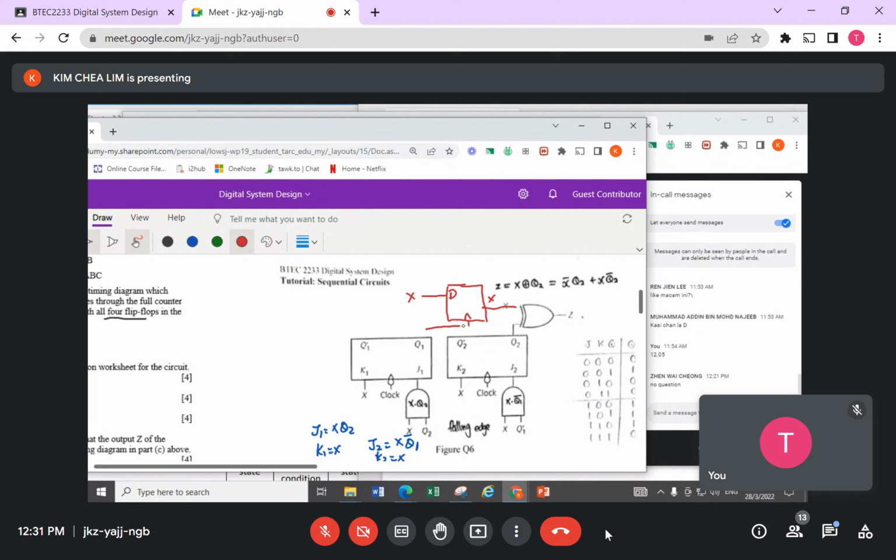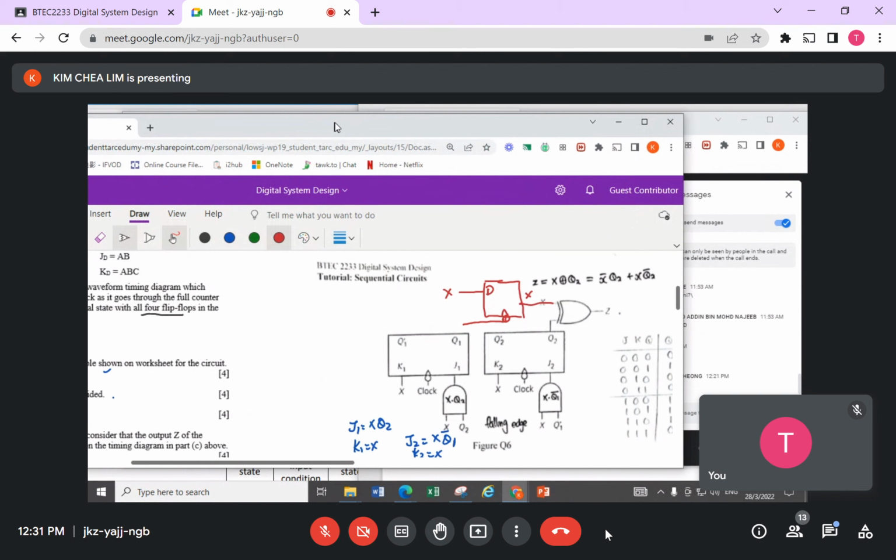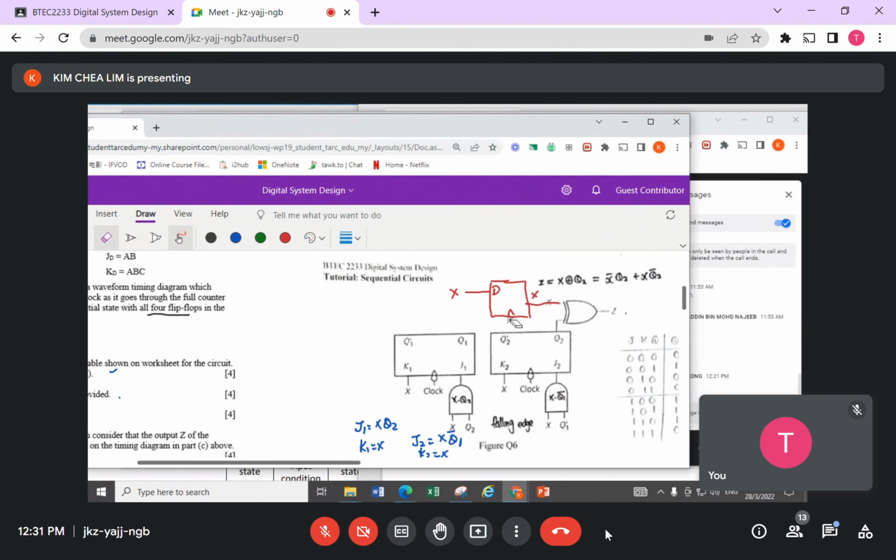And X only comes in, controlled by the clock input. The original circuit here, the clock is just coming as they like. So when they come in that time, this one here is controlled by this clock. But this part here, no. So in order to do so, we also make this X input here controlled by the clock. If this is the active low, or falling edge clock, I make sure that this part also uses the falling edge clock as the control.